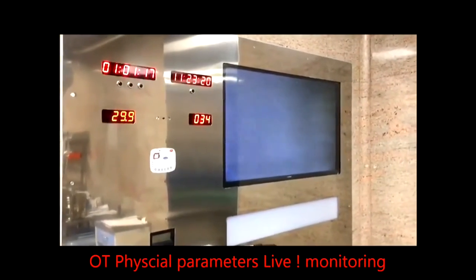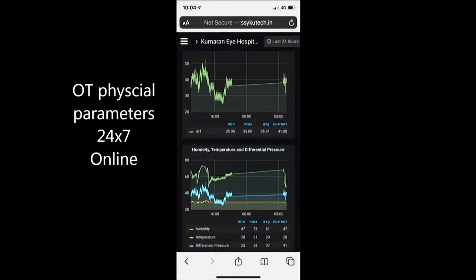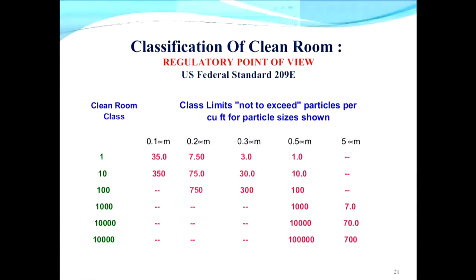It is very important that the pressure is monitored throughout the running time of the theater. This is a portable device installed inside your theater, which monitors the differential air pressure. This video shows that on opening the door of the theater, you see the drop in pressure. From 5, it drops down to 1, and once the door closes, it comes back to a positive pressure of 2.5 to 5 pascals. This differential pressure is constantly monitored and stored in the cloud for you to retrieve, and it also sets up an alarm to show when the pressure goes beyond the limits.